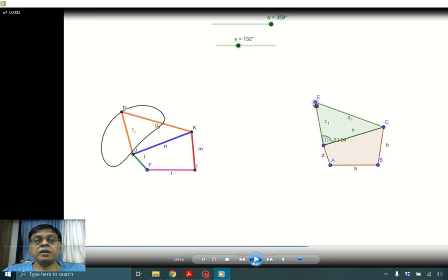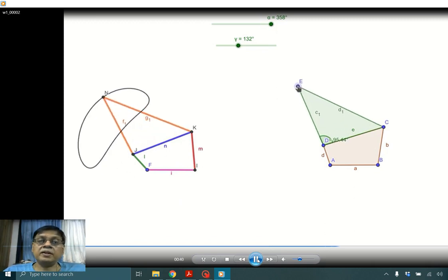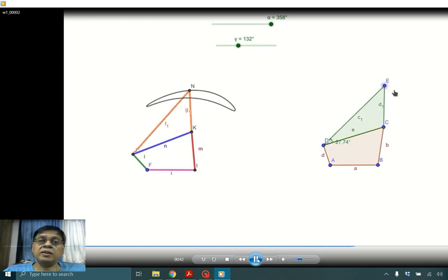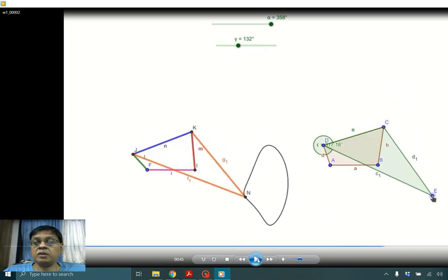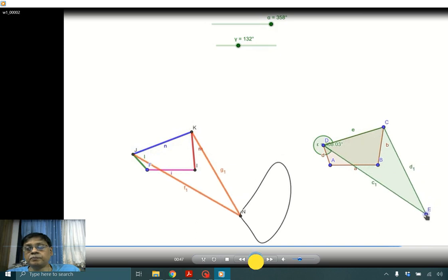The ellipse is becoming like a kidney bean shape as we roll this coupler point, and I have just pulled it further, and you can see back again these kind of curves that come. So this is another case where I can have a straight line like this or a straight line like that. Over here you can see that that part of it is straight, so you can see that the complexity of the coupler curves is visible in this kind of a video.